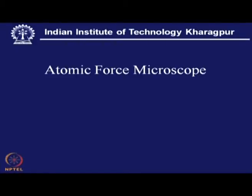Now, the atomic force microscope, this is a very recent development. In this case, when it is a surface coating, with the fineness of all coating technology, with refinement of all the processes, one can also go to characterize that surface at the atomic level. That means, just to have detail about the top layer atomic arrangement, and that is also a kind of surface morphology study or surface irregularity study, of the arrangement of the atoms.